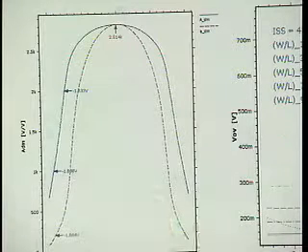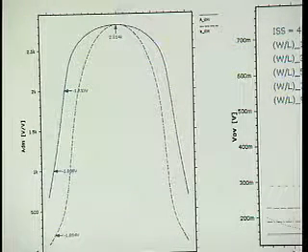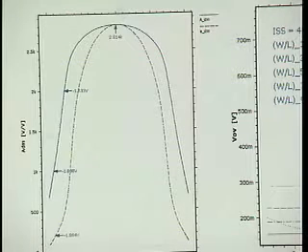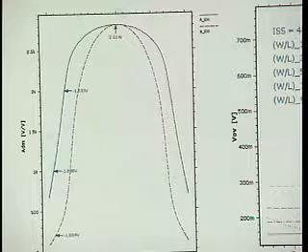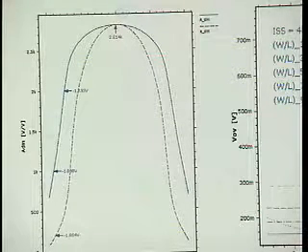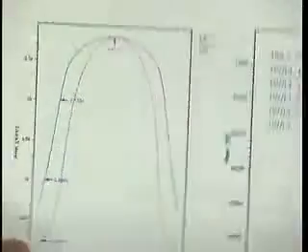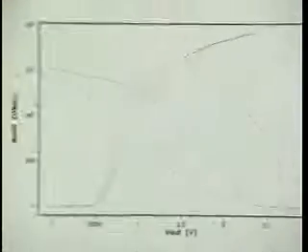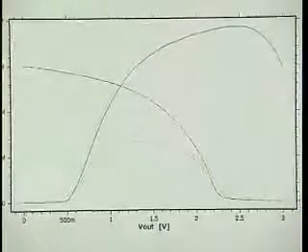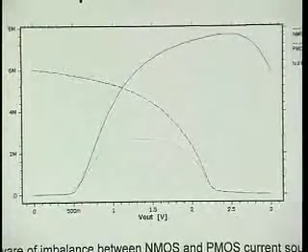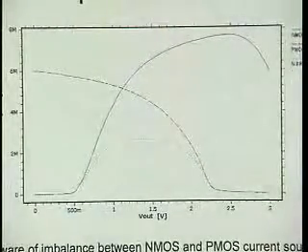But if we wanted to get more than a gain of 1,000, we probably would need gain boosters or a second stage, because beyond that, if you double the channel lengths again, you get maybe twice the gain, or not even quite twice the gain. Now it becomes sort of not that effective. You can play with this. Another important thing that is easy to forget, and then we are starting to fight windmills, is: okay, so now we want to improve the gain.